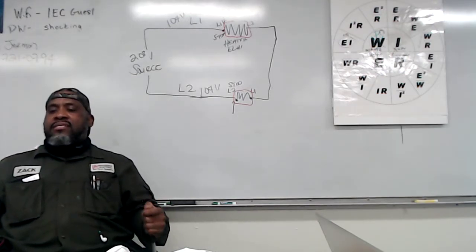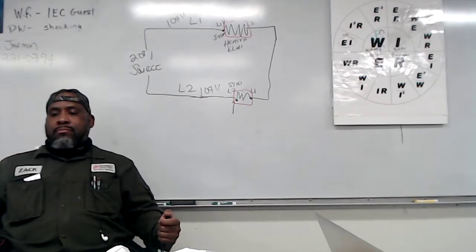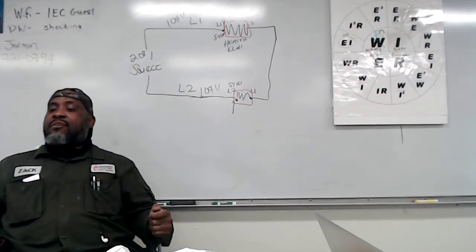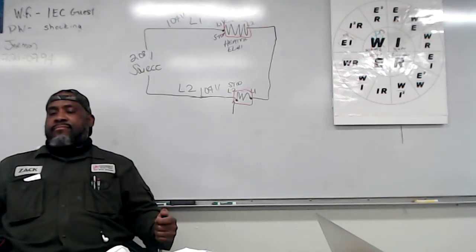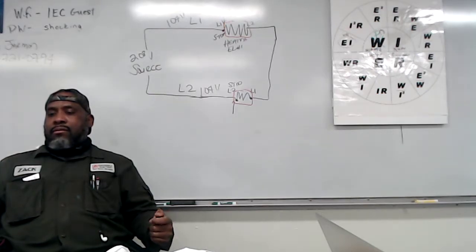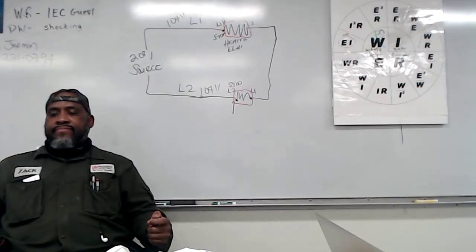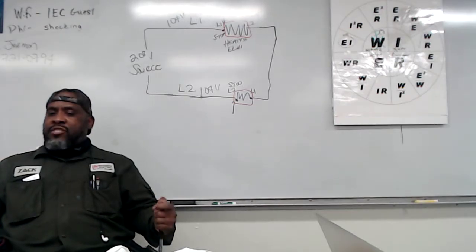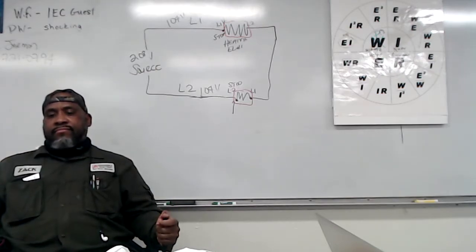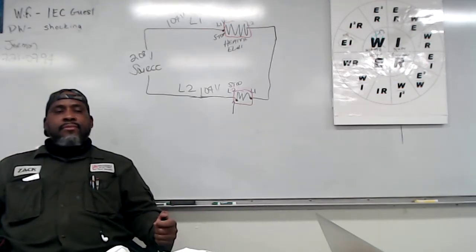So on that same problem, what points will have power on them? T1 and T8 only. That'd be half of the rating on those points, right? Yeah, it'll be 277, right? At T1, 277, T8. Half of 277. Wouldn't it be half of 480, so maybe 240? I'm sorry, 240. And that's only when we're dealing with heating elements.